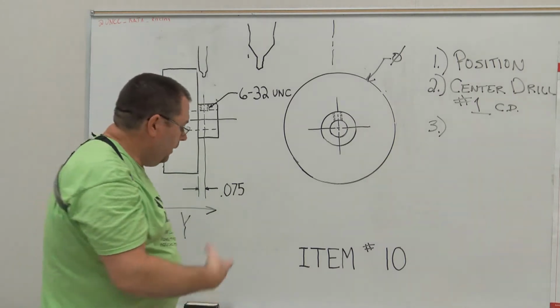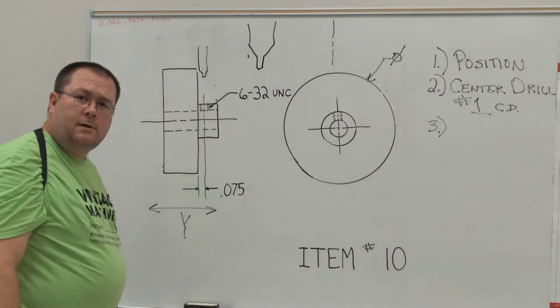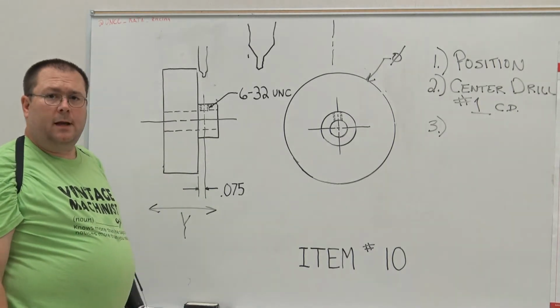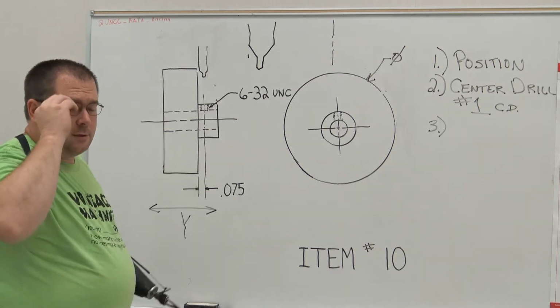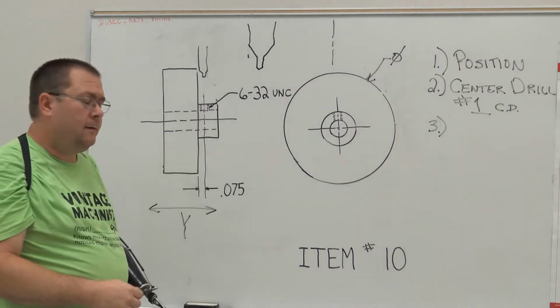A split point, put in a hand drill and I touch, it's going to start drilling right where it sits down. It's just a better way of drilling holes, a lot less cutting force. Cutting force reduced, heat reduced, okay?